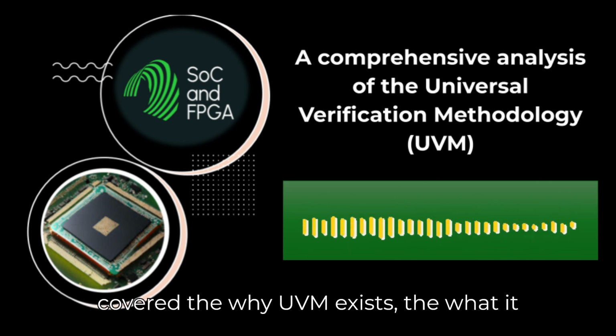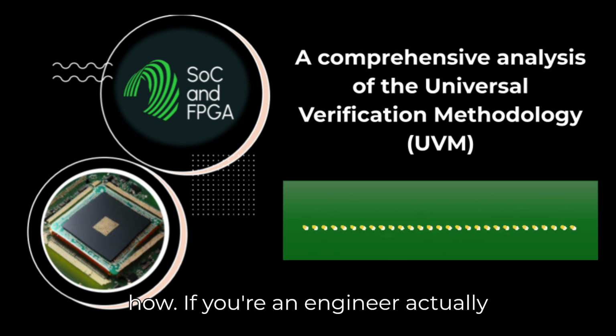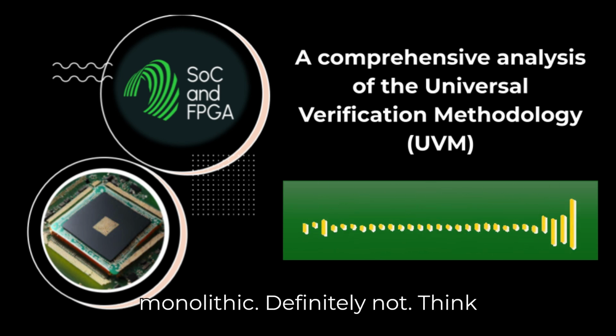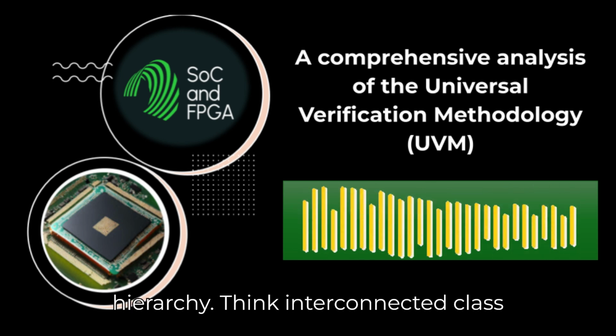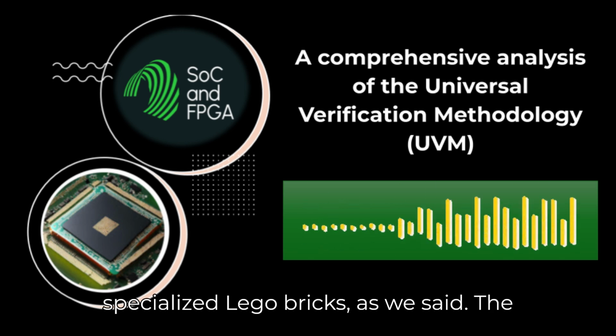Okay, we've covered the why UVM exists, the what it is, and the tools. Let's dive into the how. If you're an engineer actually building a UVM test bench, what's the typical architecture? You said it's not monolithic? Definitely not. Think hierarchy. Think interconnected class-based components, like building with specialized Lego bricks, as we said.